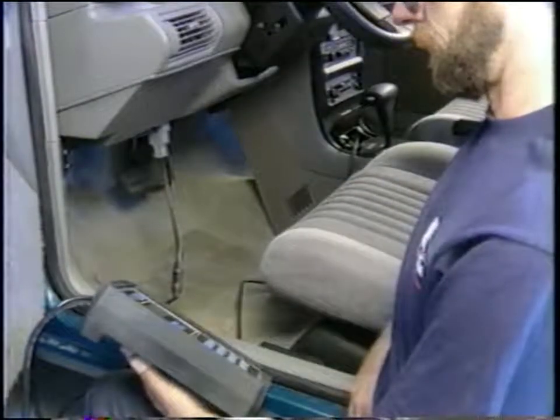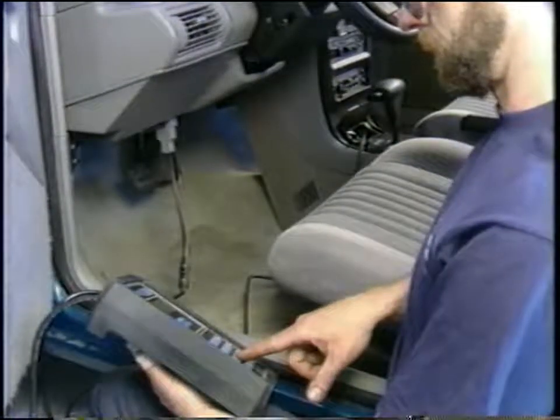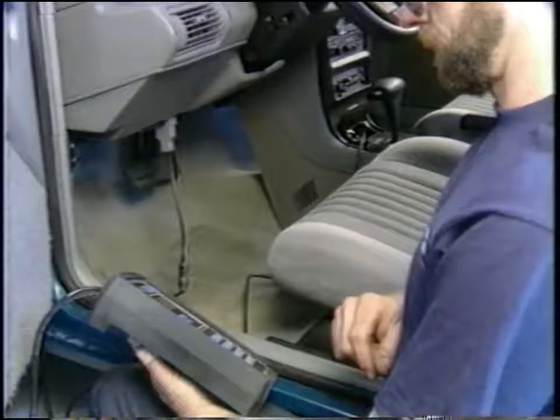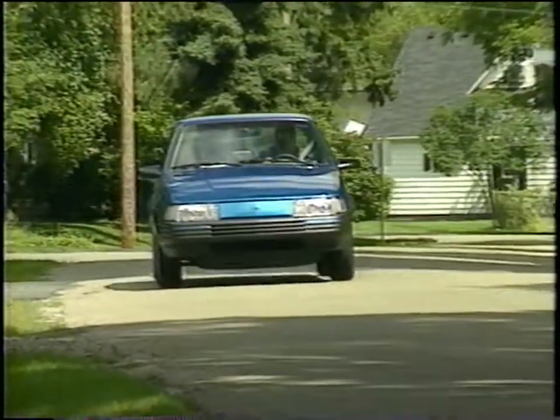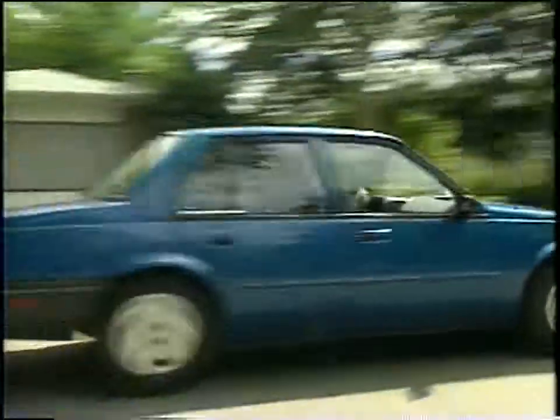The rear pistons are returned to the home position by choosing the manual control mode from the ABS test menu, then commanding the rear motor to drive the pistons to their home position. The pistons can also be homed without a scan tool by driving the vehicle above 3 miles per hour. This causes the ABS module to reset the system by homing the rear displacement pistons.